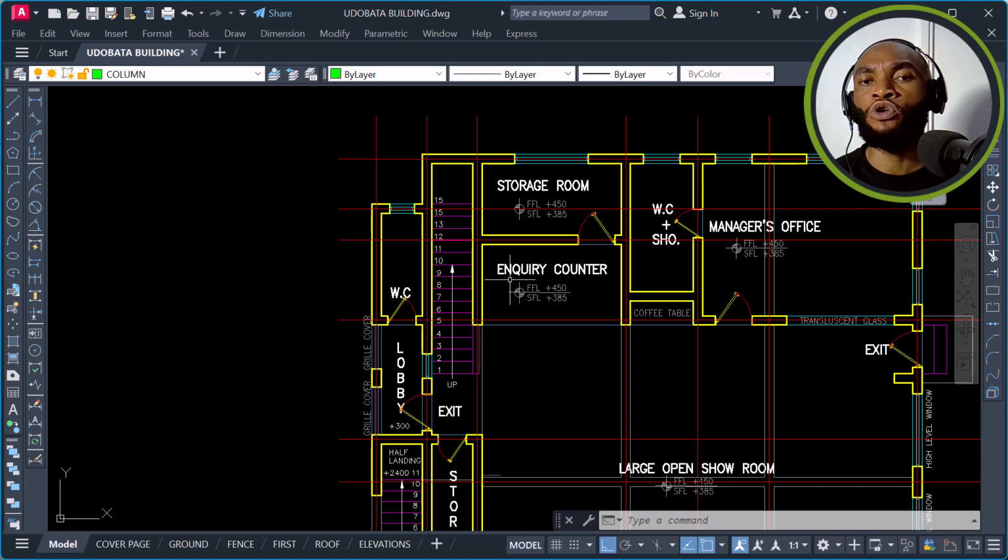If you still want the column to hide inside the block wall, instead of increasing the square column beyond the block wall thickness, you increase one side of that square column, and once you increase one side it becomes a rectangular column. Although there are some situations where you have to start your assumption with rectangular columns.